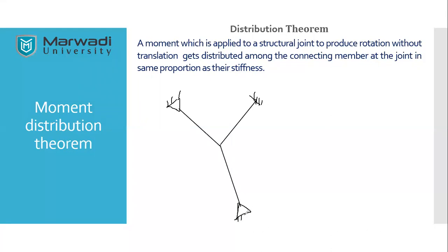And this is again a hinge support. So on what factor the stiffness depends, that we should be very clear with first of all. If we look at the formula of stiffness, it was some constant, either 4 or 3, into EI divided by L. So this is how the stiffness goes.